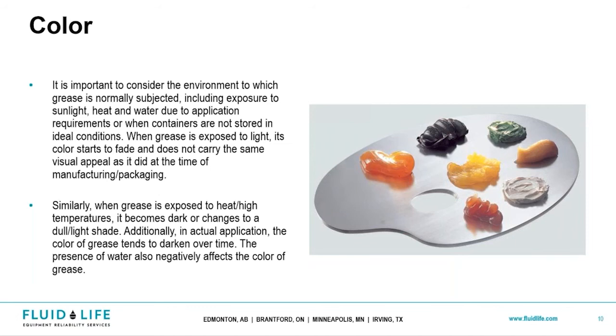Now, keep in mind, color. There's a lot of different dyes. There's a lot of different additives that are changing color of greases, right? And some of this stuff can be just natural, and some of it can be abnormal. So it's really just a rudimentary test to get your feet wet and understand that there are changes that are undergoing versus new stock base.